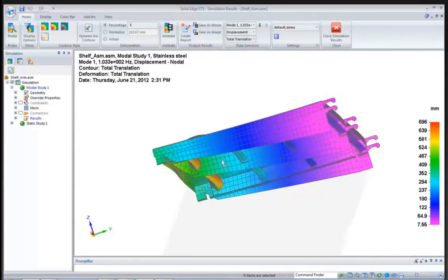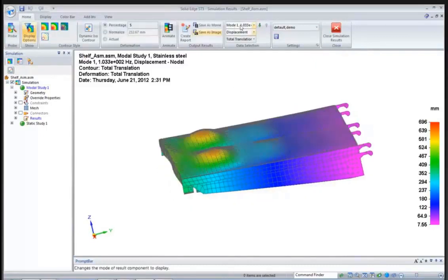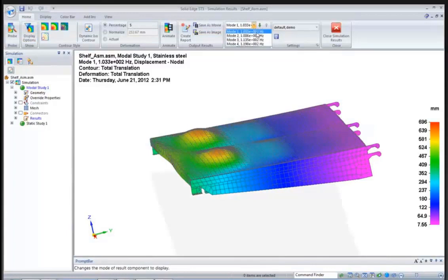So what I did is I added another bracket there, because now it's constrained. So now it's stiffer here because it's constrained here in the middle. And I didn't increase the mass too much, and I actually went to a 20 gauge sheet metal, which means my part is now considerably thinner. My parts are now considerably thinner than they were, so I'm saving in material costs. And if we take a look at this mode, you can see now that the mode is up at 100.